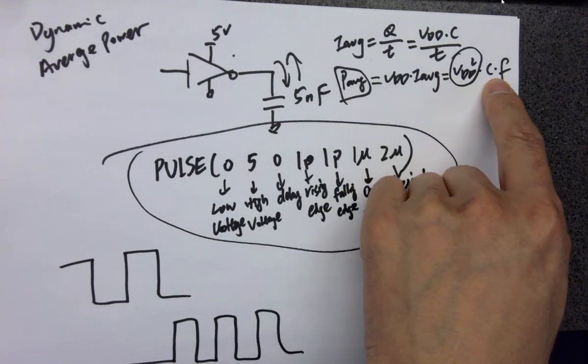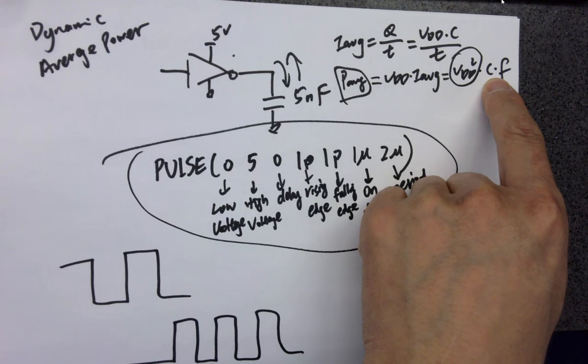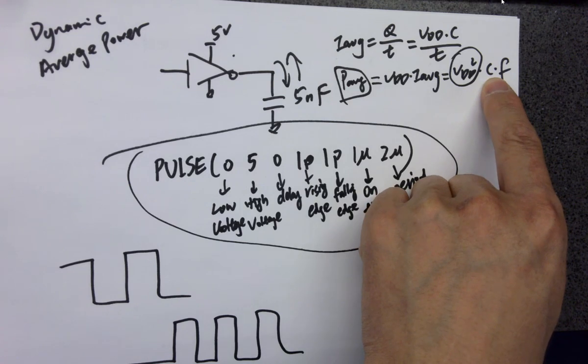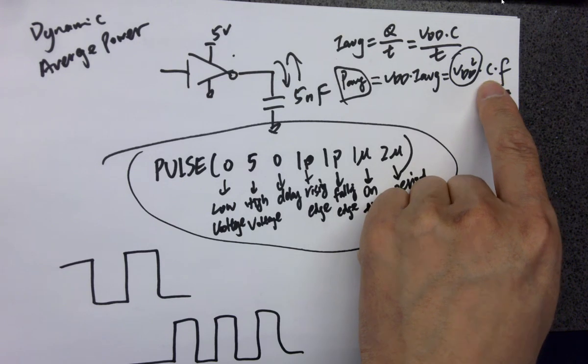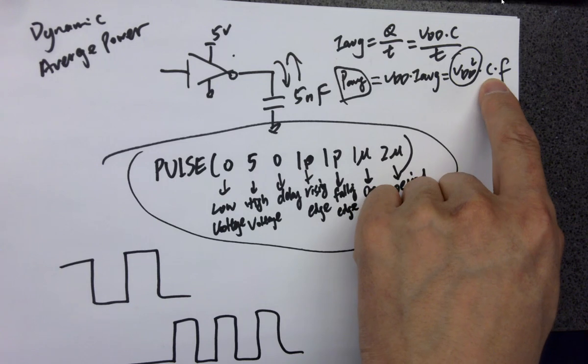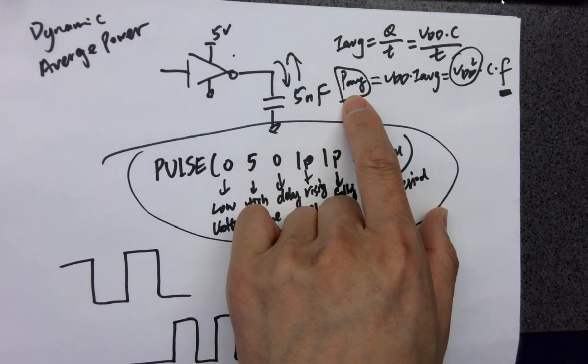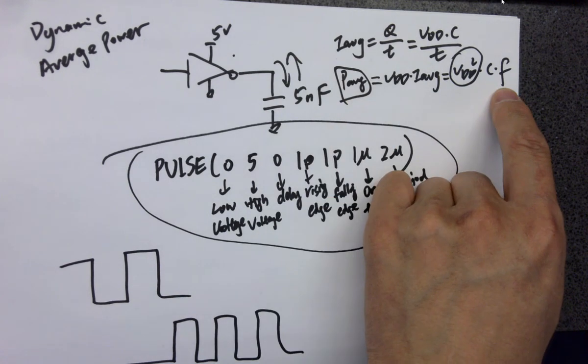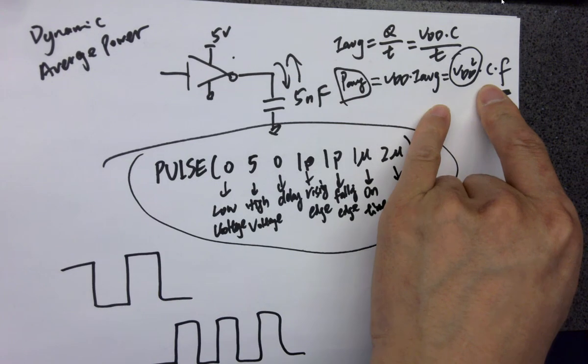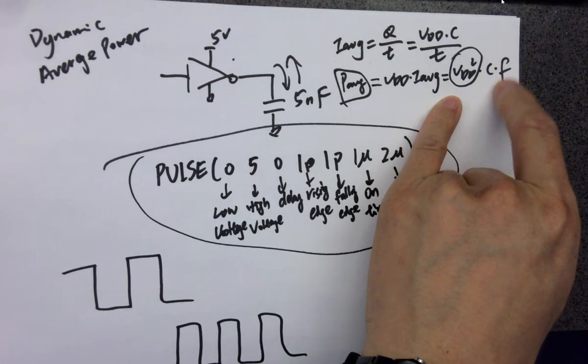And for capacitance, we know that for a smaller gate area, we get smaller capacitance. So smaller transistors give you smaller capacitance. By reducing VDD and reducing capacitance, and running this faster, you eventually get the same power consumption, but you are running it faster. That's the advantage of using smaller technologies.